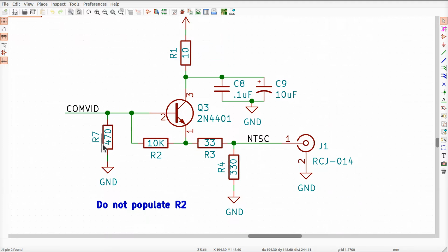If you don't populate R7, and you short R1, and you don't provide these capacitors over here, or even if you do, it wouldn't make any difference in that scenario, right? Short R1, open R7. These resistances here are the same values that you see in the Steve Ciarcia article. If I put this resistor in my design, the noise that comes out over here goes way up. So I don't even know what this is for.